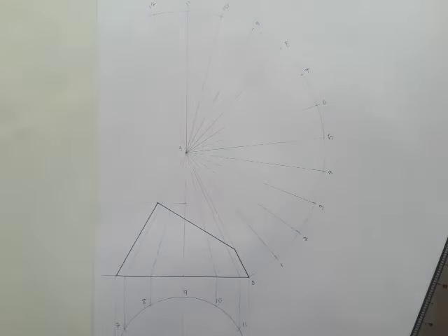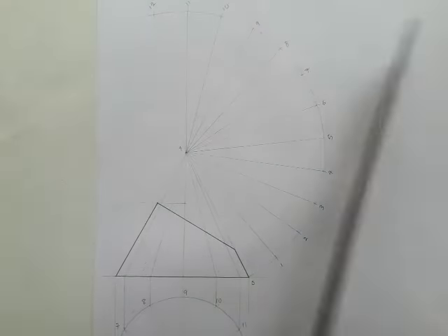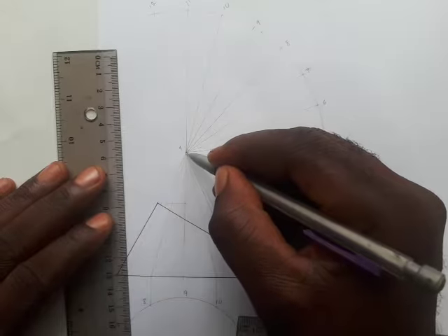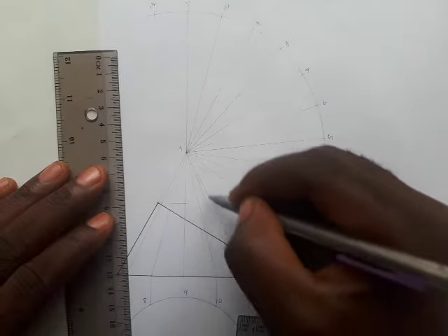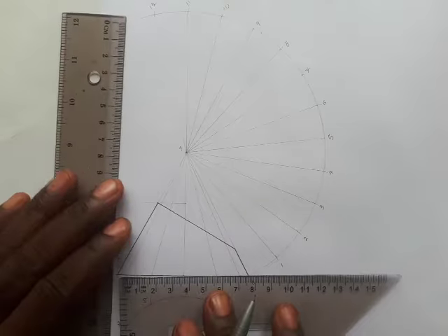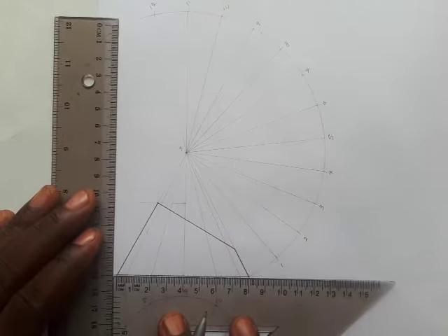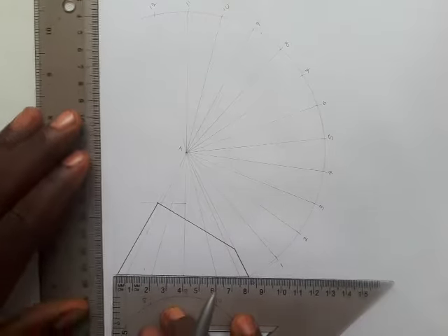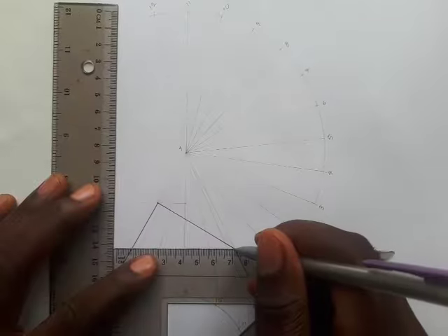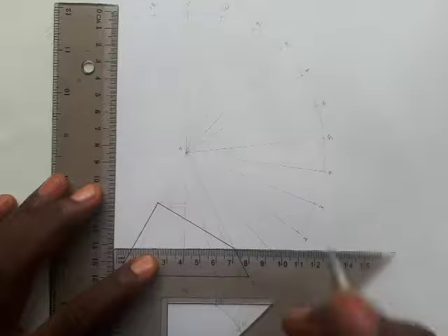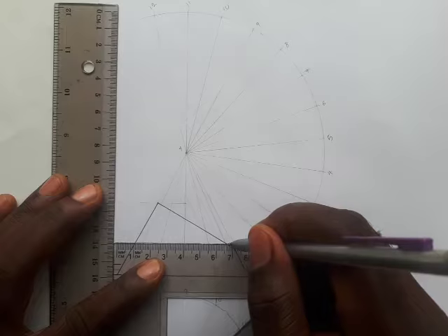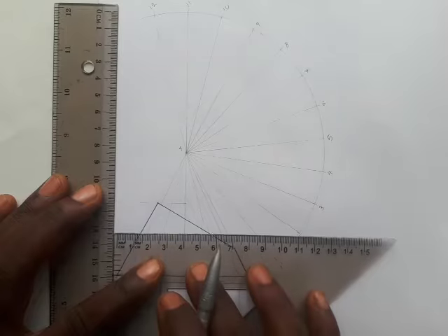No, it is wrong. What you're supposed to do actually is to draw lines from all of those points to touch the slant side of this cone. How? You align your set square with the base, because they definitely have to be parallel lines to the base. So you support with your ruler. Then this is already on the slant part of the cone, so you're not going to draw any line there. So you move to the next one, which is this one. So you draw lines from this point to touch the slant part of the cone.